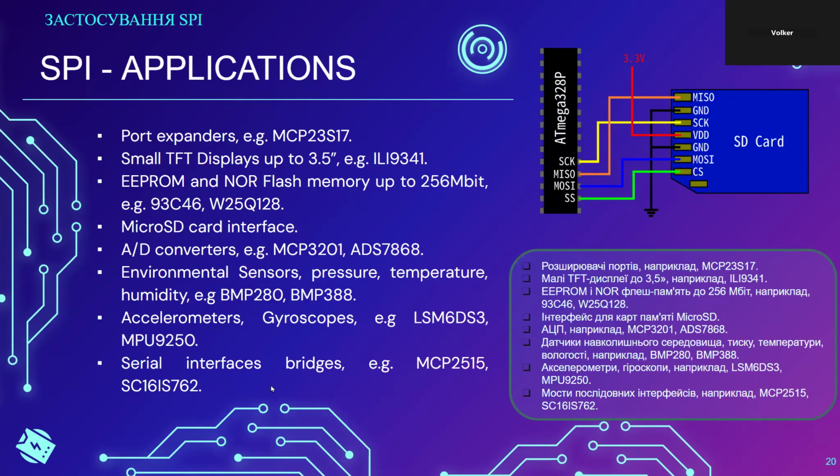Again, these are examples; if you put these names into AliExpress, DigiKey, or vendor websites, something will pop up that might lead to other devices too. These devices generally have both an SPI interface and an I2C interface. In most cases, you would rather use the I2C interface over the SPI interface, but it does have an SPI interface.